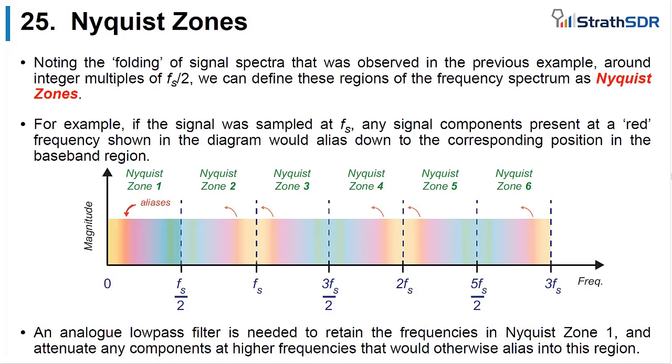So Nyquist zones, we can go to higher Nyquist zones. We will limit ourselves at the moment to Nyquist zone 1 and Nyquist zone 2. That's what David will show you. But in theory, we can go higher. And that's something that will undoubtedly happen over the coming years as the analog front ends get faster and faster.